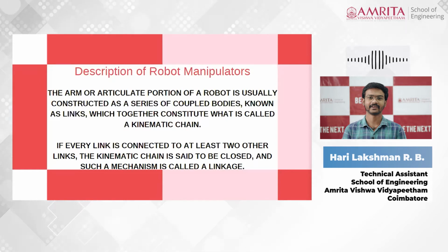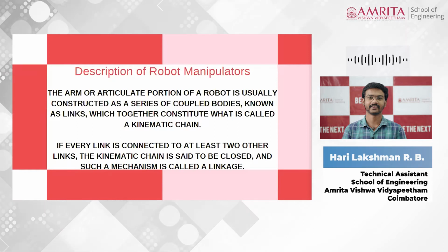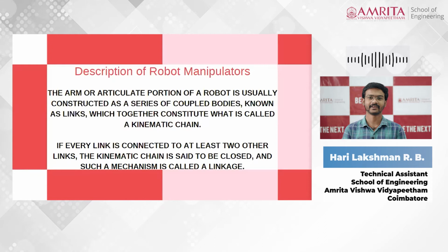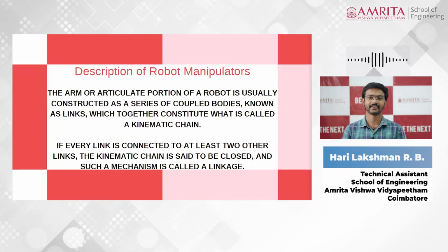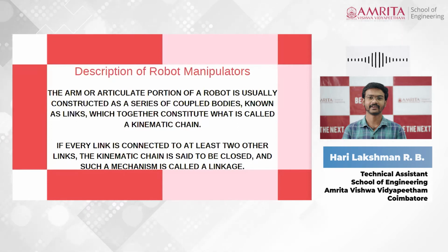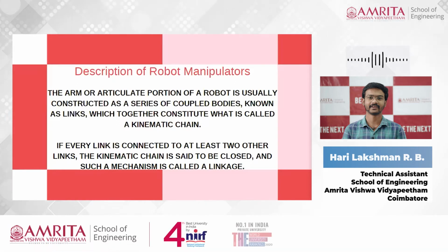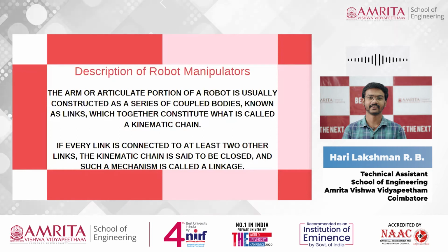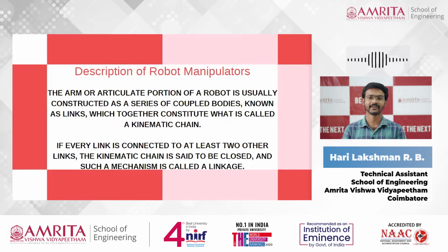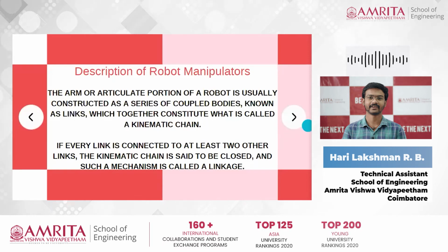Okay, however, since kinematic and dynamic analysis of a closed kinematic chain is involved, most industrial robots have open kinematic chains only, and that's what a manipulator is about. So manipulators are nothing but completely open chains, with some form of end effector attached to the final link. Depending on the intended application, the end effectors are being used. And so we usually refer to this class of industrial robots as robot manipulators.